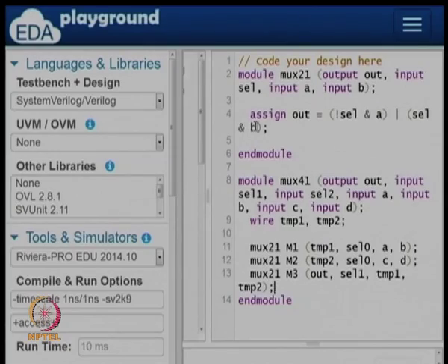So I will leave the video at this point. At this point you have the basic infrastructure to run Verilog, and I suggest that you go and take the Verilog files and run it yourself and check whether the outputs are as expected or not. If you want to try it, go and write your own mux 4.1, right. You can delete the mux 2.1 and you can write a Boolean equation for mux 4.1 and check whether your Boolean expressions are correct or not, right.